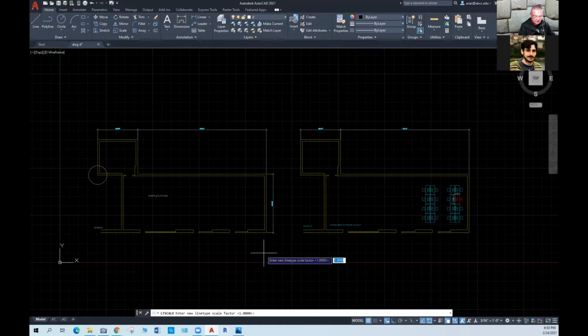It just sets it to that. And then also it creates problem with other variables we're going to talk about. So in my opinion, if you set the LT scale to 1, then you have more control. Although some companies may do it different ways, right? And so that's all I'm trying to say.